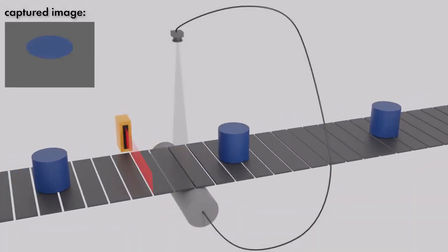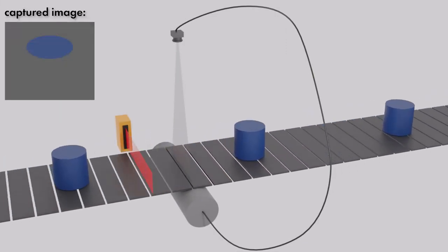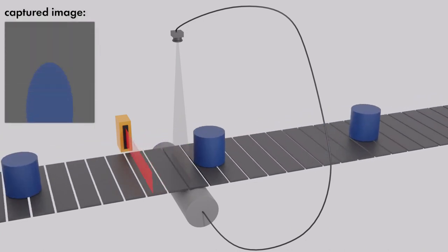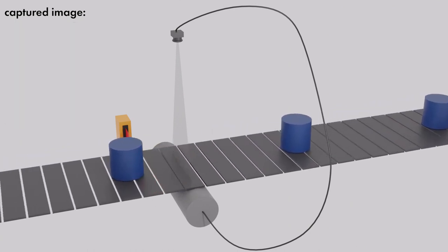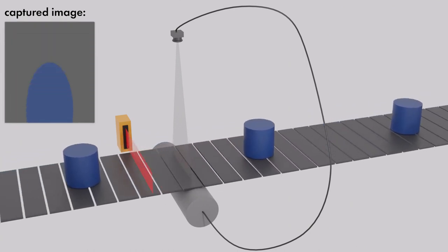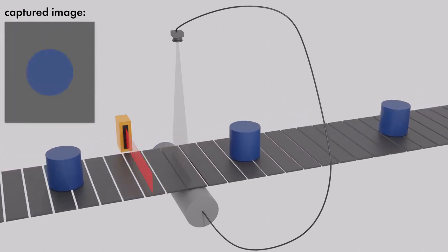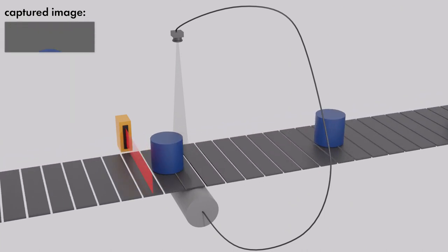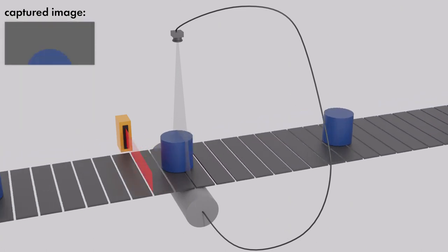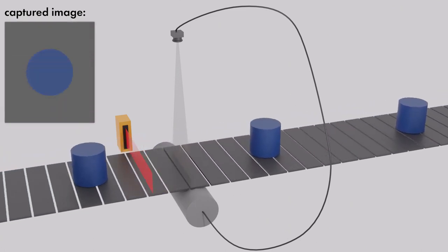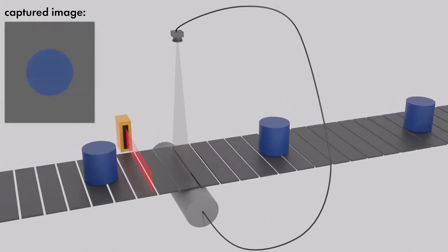If the movement speed of the object is too fast for the line acquisition, the acquired images will be compressed. If the movement speed of the object is too slow for the line acquisition, the acquired images will be stretched, or worse, won't be fully captured, like in the animation shown. In real-life application, the movement speed of the object won't even be constant and will vary. Therefore, to prevent distortions within the 2D images, an encoder is used to synchronize the varying movement speed of the object and the line acquisition rate.